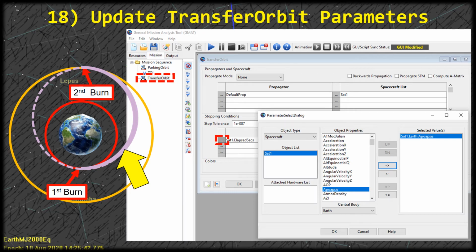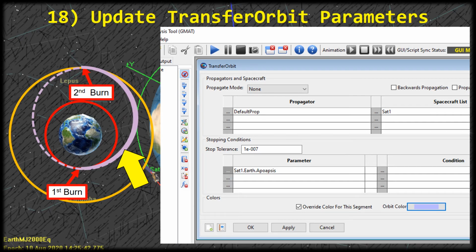That's the idea behind this Hohmann transfer, is that we start at the periapsis of the orbit and we size it so that we get to the apoapsis of the transfer orbit when we're at that point where we want to switch to the final orbit. So find apoapsis in the list and make sure the central body, of course, is Earth. Don't forget to click the arrow to actually change the selected value there on the right column. And then when you do that, click OK. You'll see that the stopping parameter changed to apoapsis.